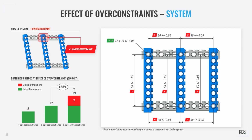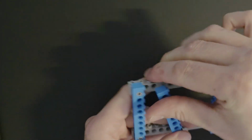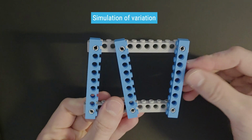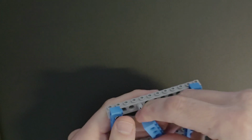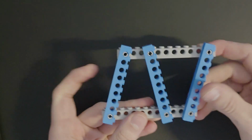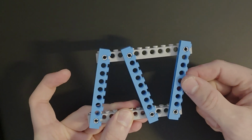That means that we need to control all interrelated dimensions. If just one of the dimensions is off, the mechanism will not move freely. In fact, in the worst case, the mechanism will not move at all. It will be a structure. It looks like a bike frame or an element for a bridge. And this is just with a single overconstraint.